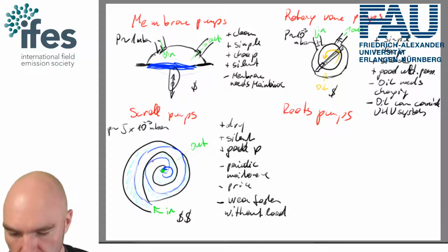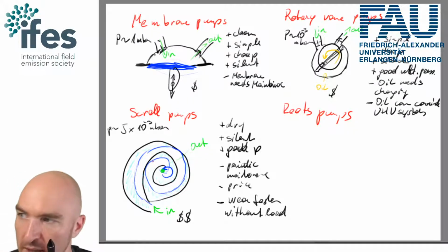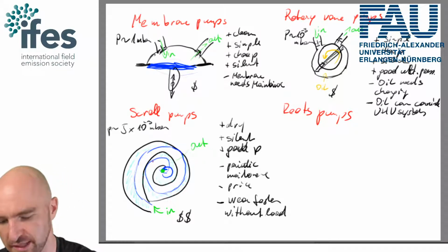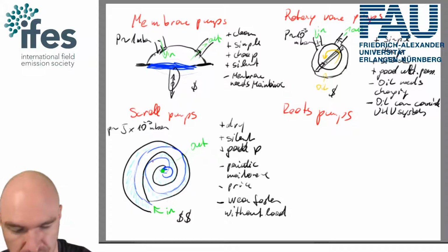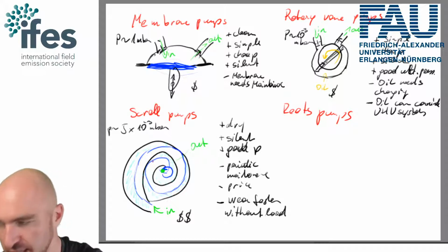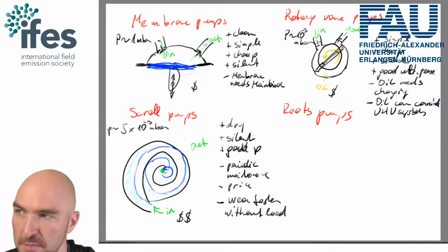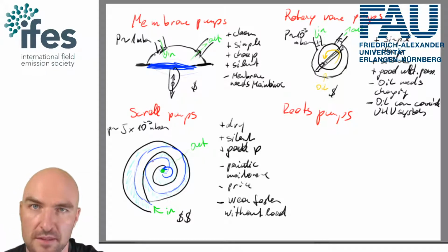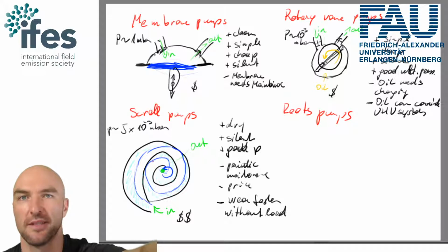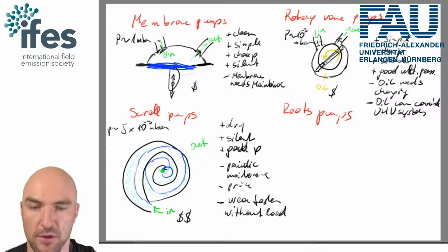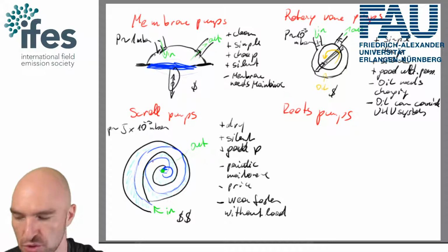Yeah, so they have that problem, even though on our pumps we didn't. If you get the good ones, then that problem is not super bad, but it's still there. This makes these pumps very good, for example, if you want a system with only a load lock, because you periodically pump the load lock from ambient pressure, which clears out all the dust, and then you don't have too much of a problem. So scroll pumps are a pretty good choice.